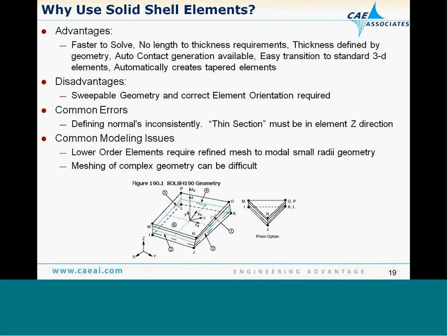The elements solve fast, since we can use a lot fewer of them because we don't have to obey a good aspect ratio through the thickness.